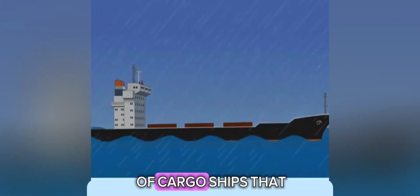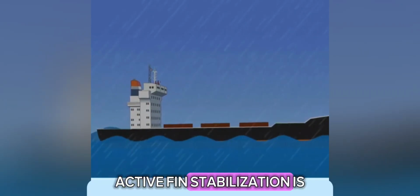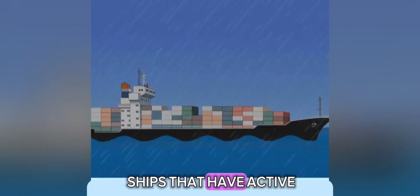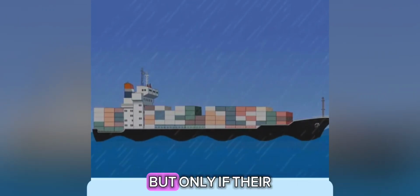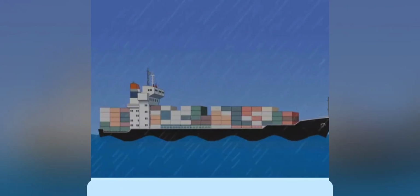So, in the case of cargo ships that usually travel at slower speeds, active fin stabilization is not installed. However, there are container ships that have active fin stabilizers, but only if their average cruising speeds are high enough to maximize the benefit.